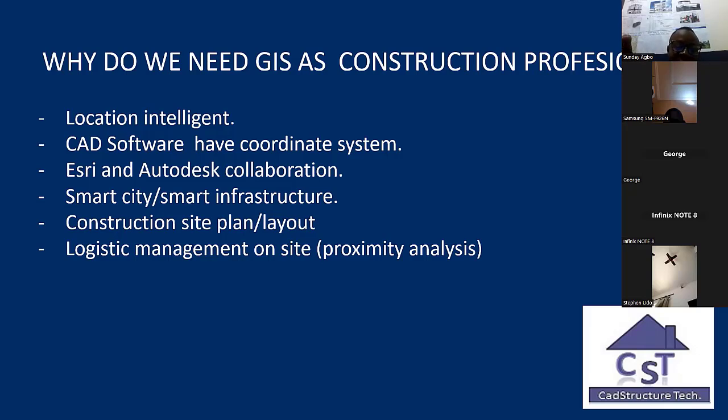What I mean by real-time data is that if you are using AutoCAD, you are not possibly designing it on a satellite image. But if you are using GIS, you are designing it on a satellite image, directly on the exact position where all those features will be. So if your proposed building is 10 meters by 10 meters, you are bringing out that 10 meters by 10 meters in the exact location using the coordinates that you have, so that in terms of movement of trucks or machinery within the site, there will be no obstructions, because you are using real-time information to do your site layout.